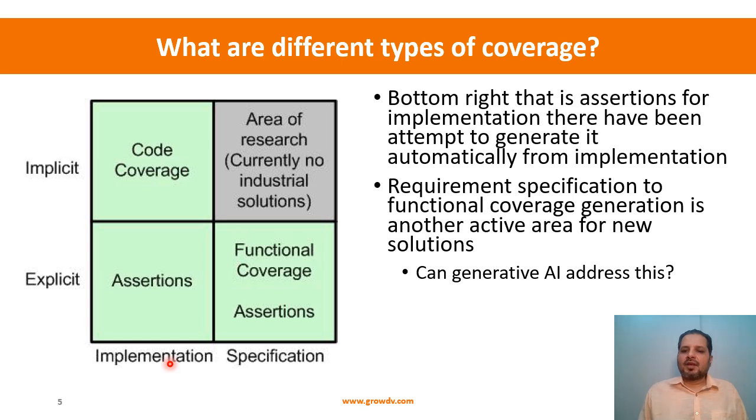Now if I implement that buffer in the granularity of 256 bytes, then the number 256 becomes an important number. If I get a packet that is 257 bytes, then I need to allocate two buffers to store that packet. So at multiples of 256, there is some level of change in the way this particular architecture processes the packet.